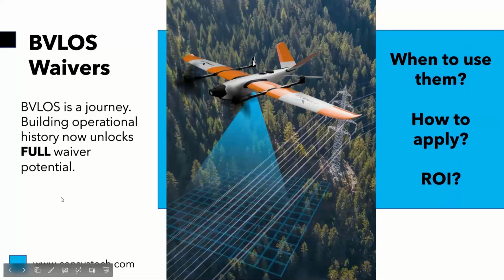So the next waiver we'll discuss, we've kind of hit high altitude. We will talk about BVLOS waivers. 107.31 and 107.33 is usually right on its heels. So 107.31 covers the line of sight regulation, get that waived. 107.33 covers the visual observer regulation, getting that waived as well.